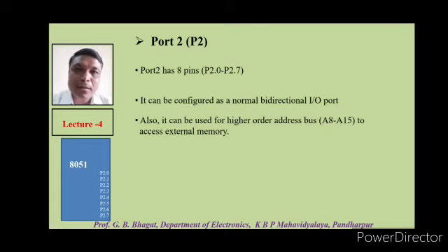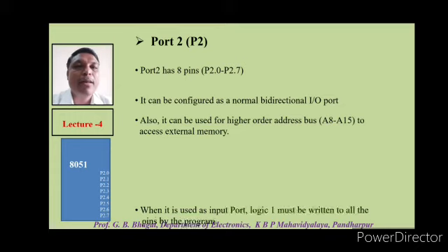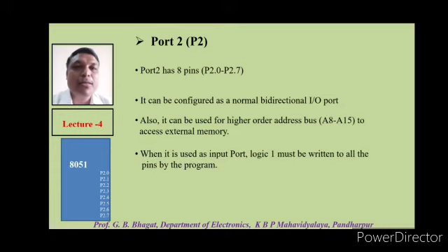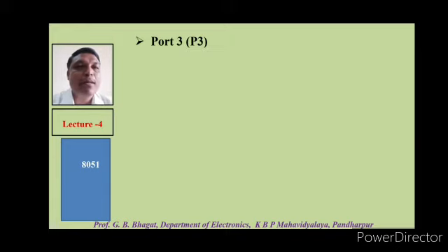That is, if we are going to interface external memory to the controller, then this port can be used as a higher order address bus along with port 0, because port 0 is used as the lower order address bus, and port P2 will work as the higher order address bus. When it is used as an input port, then logic 1 must be written to all the pins by the program.